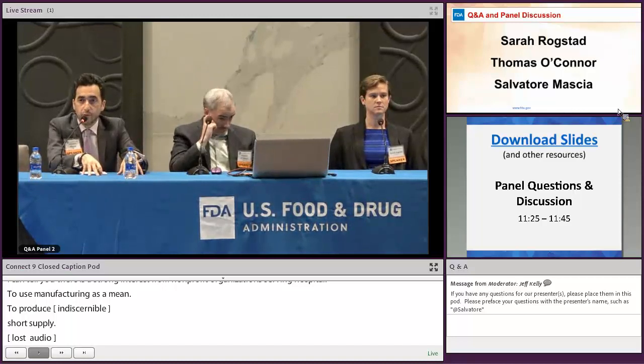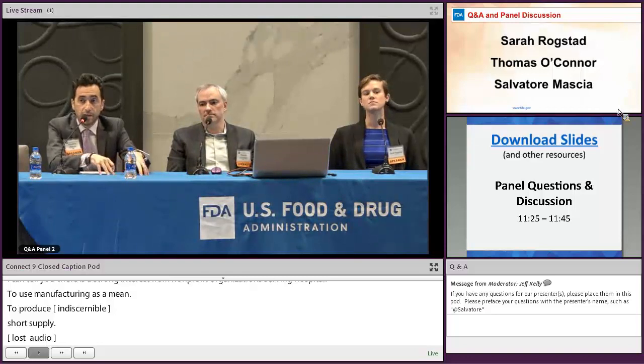Then when we develop the process, we perform a lot of analytical testing offline with conventional offline techniques like HPLC, GC, X-ray, and then we match those data with the inline PAT sensor that we're using to monitor this quality attribute, such that when we integrate the system and run the process, we can identify this out of specification material, so material which is not conforming to specification, through this inline measurement.